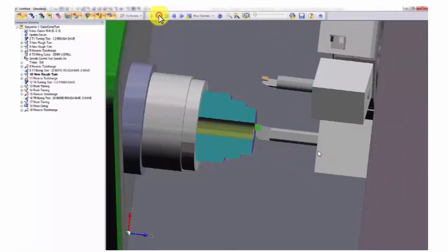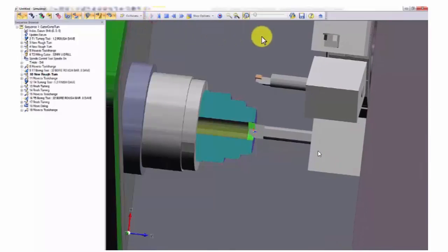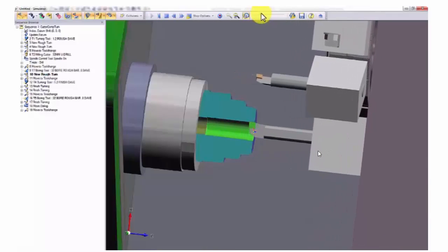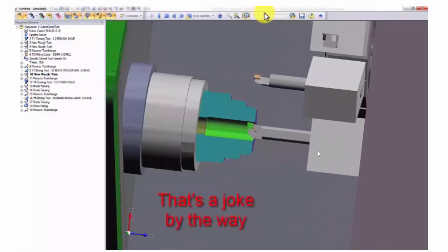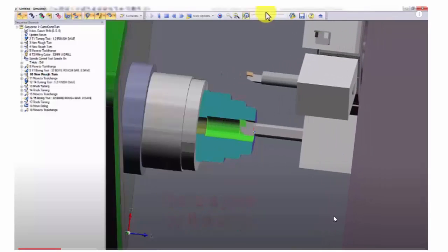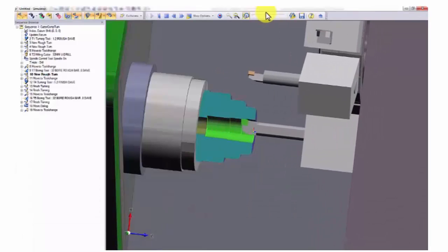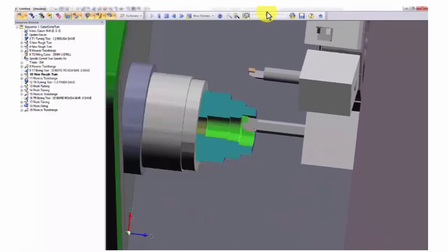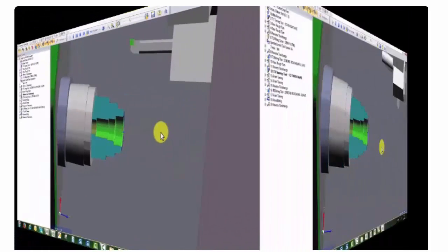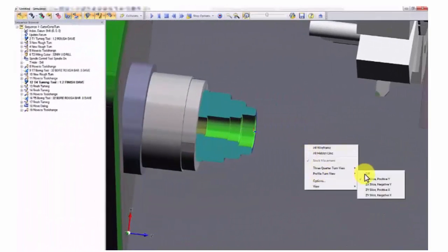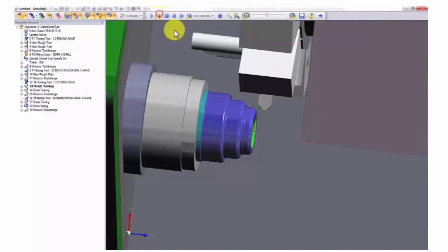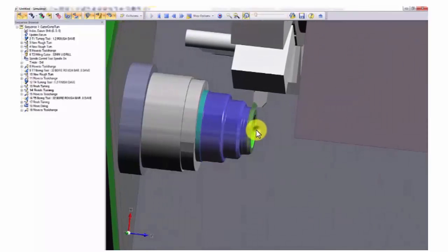Come in with a rough boring bar, a little bit long that bar, but doesn't seem to be chattering much on this simulation, so that's roughing it out. Standard G41 roughing cycle. Come in with the finishing tool, comes down, faces the part, and finish turns it. Fairly standard stuff.